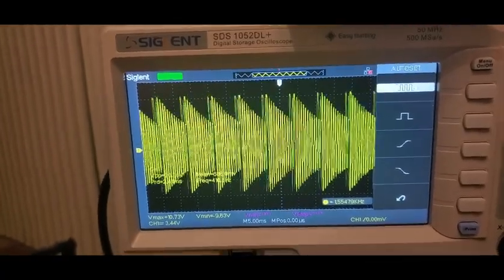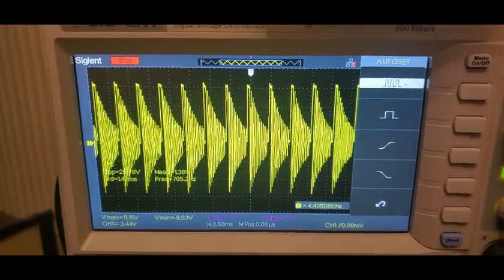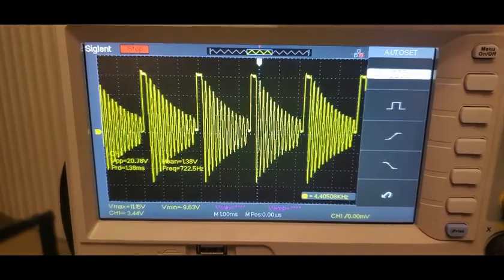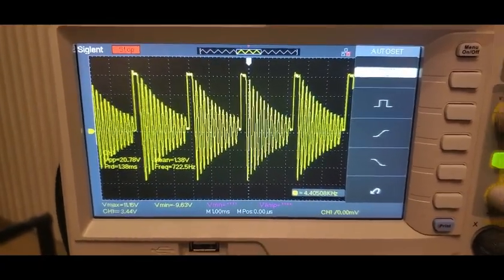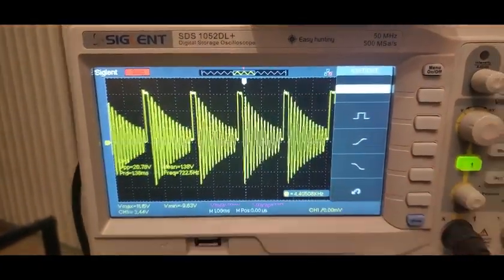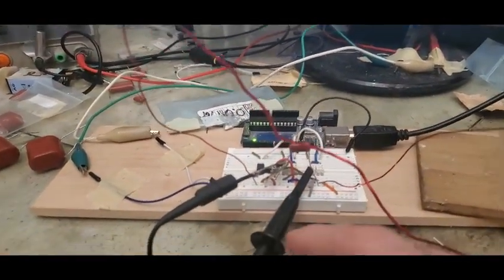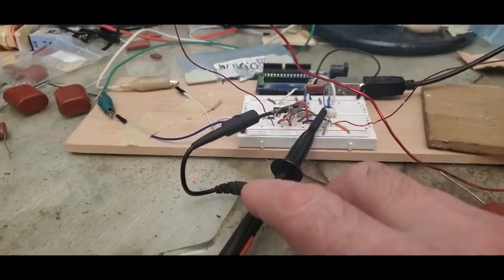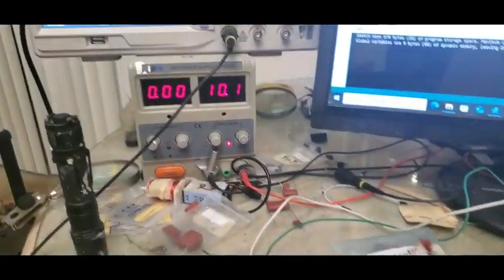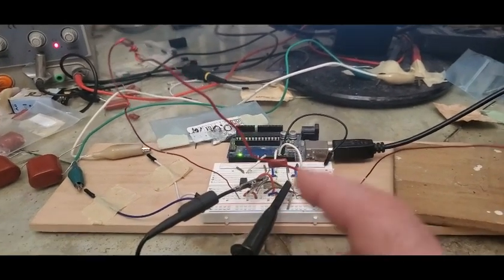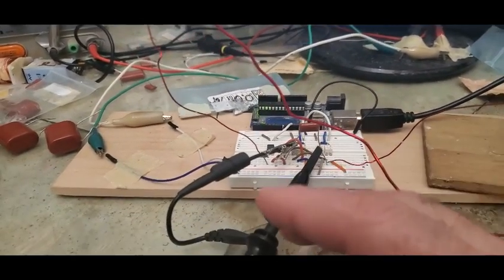Let's go to 0.01 µF. So there's 0.01 µF. Wah, wah. So now it's getting worse. The thing that I wanted to figure out was, is it leaking out? And you have 10 megohms of resistance here, and we're at 10 volts, so it's a 1 microamp draw. You can do the math and figure out, no, it's not leaking out that much.